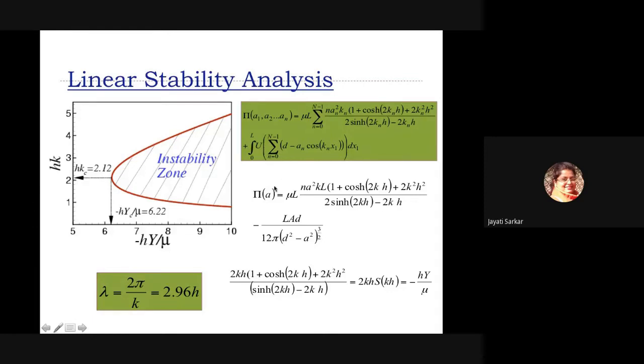What type of instability we will see depends on the optimized Fourier coefficients that we obtain if I try to minimize this energy. That can be done by a conjugate gradient method that we use to find these optimized coefficients at any point of the contactor. First the contactor is brought to a critical distance, we see the instability that is happening, and then we can retrace the contactor back and find the distance up to which this instability persists, because this is what was seen in the experiments: the critical distance at which the instability first started and the snap-off distance where the instability persisted were quite different.